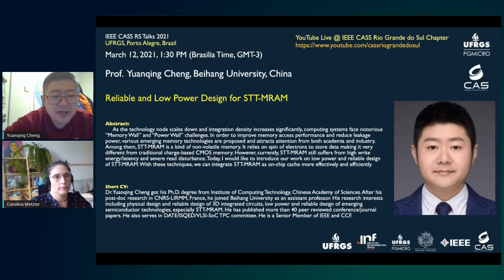Originally, the STT-MRAM was proposed to replace the on-chip SRAM as the cache memory. But I know that commercial companies like Everspin have also released commercial STT-MRAM products for main memory usage, because they can support the mainstream DDR protocols as for DRAM memory.